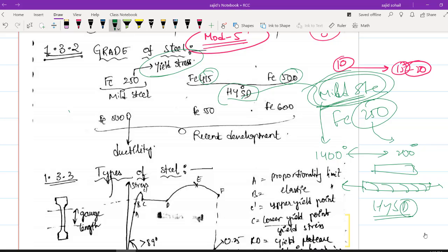You have deformed it, right? आपने twist किया हुआ है. You are twisting your steel bar. You are elongating, stretching, and twisting the steel bar. Because of this, what is happening? You are getting higher strength, and this classification we are calling HYSD, high yield strength deformed bars.